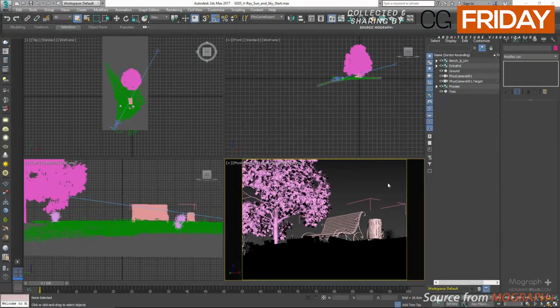In this lesson, we are going to talk about 3ds Max's light compatibility with V-Ray and basically how 3ds Max lights can be utilized in V-Ray. First of all, I wouldn't recommend using 3ds Max's lights with V-Ray even though they work, but always remember that V-Ray lights are optimized to work with V-Ray and almost all the time will give you better results.